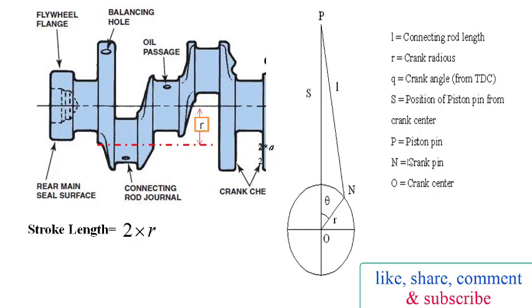The distance between the center line of the con rod bearing journal and the center line of the crankshaft main bearing journal, multiplied by 2, is the engine stroke. The combustion force is applied to the crank throw to produce the turning effort or torque, which rotates the crankshaft.